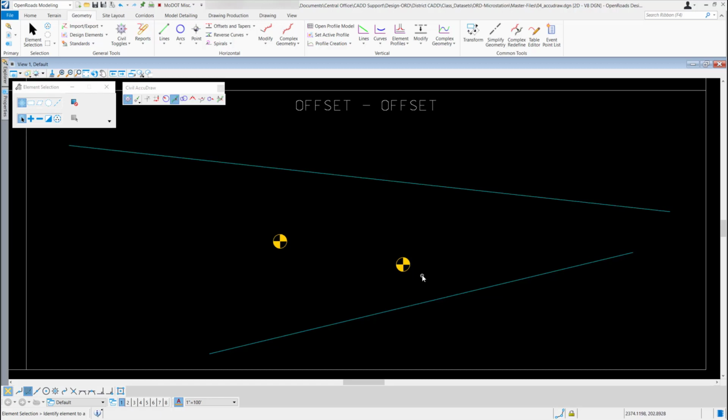So now if I just go out and select that point, you can see that there are some civil rules attached to that point based on how I drew that element. I used a 90-foot offset, and I put it at station 5+00. So now if I need to change either of those values, maybe I wanted my offset to be 100 feet, I could just left click on that 90 feet text, type in 100, hit enter, and it's going to dynamically change that distance.